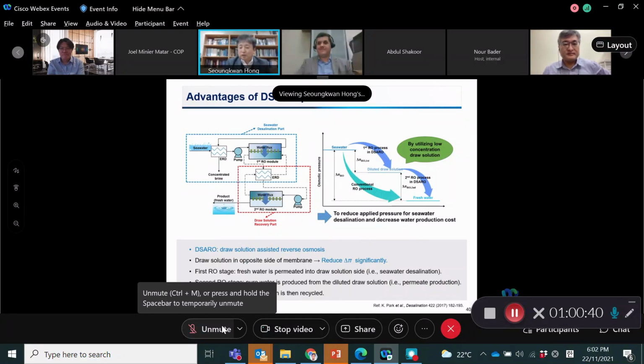So I would say, with the newly developed outer membrane, as long as the feed boron concentration is less than 5 ppm, we should be able to meet that requirement. If the boron concentration in the feed water is higher than 5 ppm, then yes, we need an additional treatment process like BWRO or CDI.